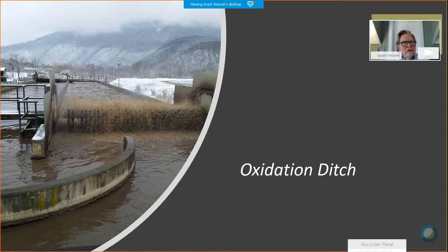You're going to have a shorter transition time going from anoxic to aerobic. In other words, when the air kicks on, the DO climbs pretty fast. DO will probably get close to your target within 5 to 10, certainly within 15 to 20 minutes. The ORP is going to lag a little behind the DO. Why is that?